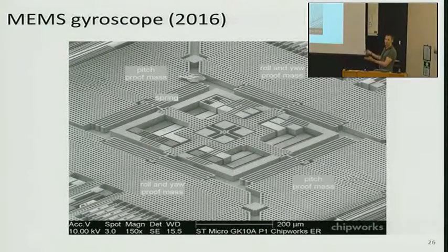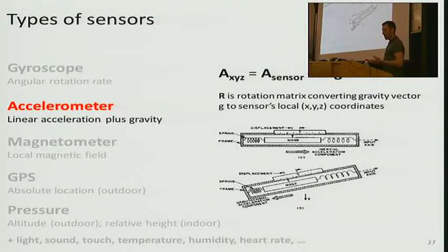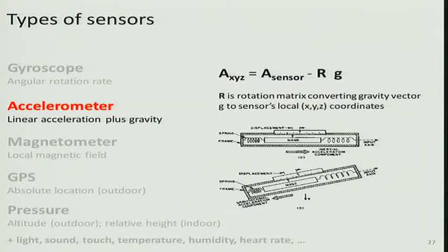So, given that this is what the technology is today, that's how the gyroscopes work. We won't look in detail at accelerometers and magnetometers, but they use similar kinds of MEMS structures. An accelerometer measures the acceleration on these small structures inside the chip, and that acceleration includes gravity.